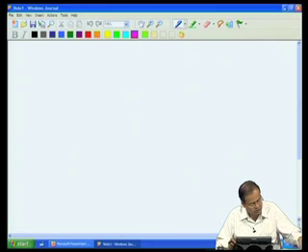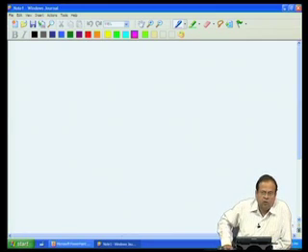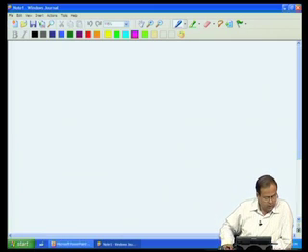So, we will see that by doing a simple mathematical analysis, and let us look at this analysis for the plug flow reactor and the behavior of the hotspot, because if you realize, plug flow reactors and batch reactors are equivalent in time and space domains. Space domain for the plug flow reactor and time domain for the batch reactor, they are equivalent. That comes out mathematically also, because your mass balance equations are almost identical, except we have real time in one case and residence time in the other case.